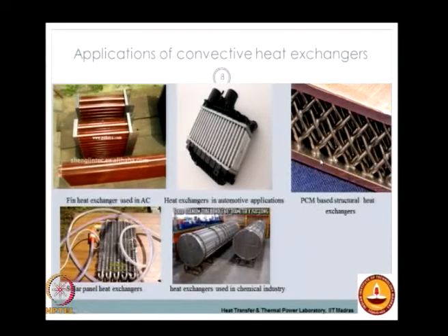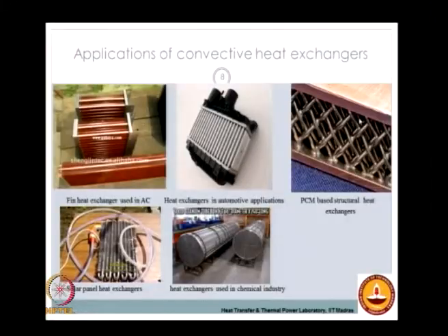You can also look at things like phase change material based heat exchangers where essentially you have a cyclic process. In one half of the cycle you pass the hot fluid through a porous membrane which could actually melt upon heating, whereby it takes the latent heat of melting from the hot fluid and stores it as a capacitor, and in the next half of the cycle the cold fluid flows through this medium, and then this releases the heat back to the cold fluid where the cold fluid gets heated, and in the process of losing the heat the phase change again happens from the liquid to the solid phase, so it solidifies.